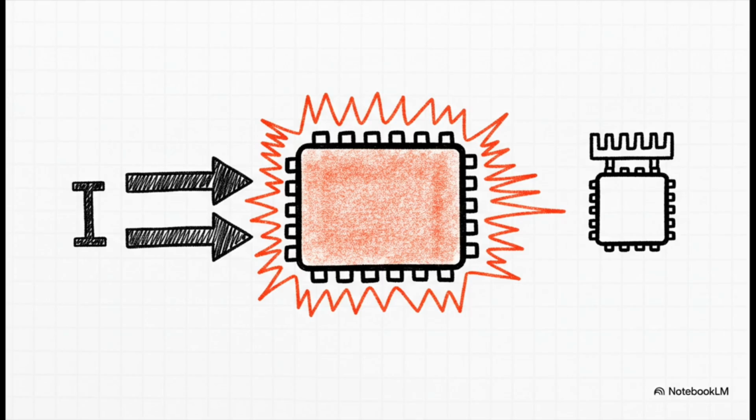Now let's talk power, measured in watts. It's the rate of work done when 1 amp flows under the pressure of 1 volt. So P equals I times E. Everyone knows that. But for us in avionics, its derivative, P equals I squared R, is absolutely paramount. Why? Because this is the formula for thermal management.